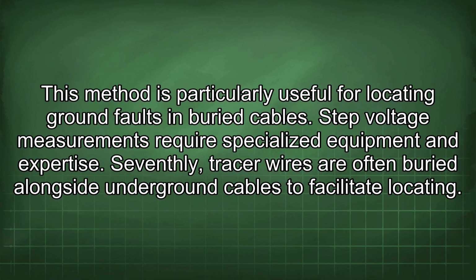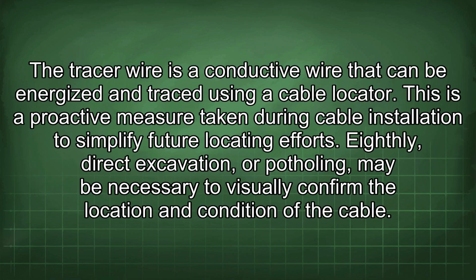Seventhly, tracer wires are often buried alongside underground cables to facilitate locating. The tracer wire is a conductive wire that can be energized and traced using a cable locator. This is a proactive measure taken during cable installation to simplify future locating efforts.